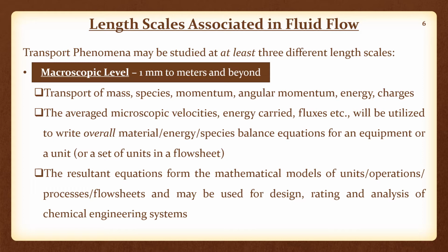If you were to measure the velocity of a particular fluid in one of the layers, the value that you use in the Hagen-Poiseuille type equation, which gives the laminar flow parabolic velocity profile at a particular position, at a molecular level, if you look at the velocities of those molecules, that velocity that you use in the Hagen-Poiseuille equation would only be an average, and there would be fluctuations around that average.